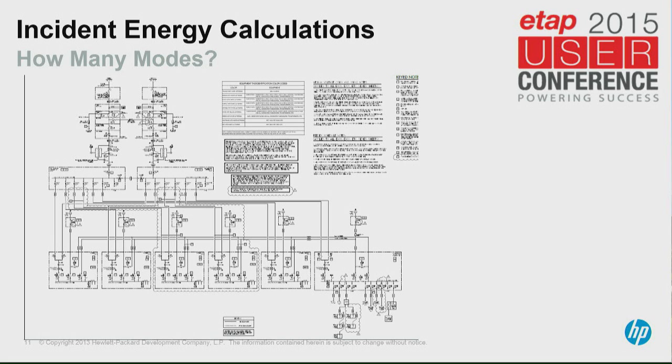When your system is a data center such as this one, how many multiple configurations do we have? What you're looking at here is an actual data center that's been constructed. It's a tier 3 data center. By the way, on the difference between tier 3 and tier 4, concurrently maintainable versus fault tolerant, this topology is fault tolerant, but we didn't go for tier 4 because tier 4 also has some physical separation, barriers and protection requirements that Uptime requires, which we didn't feel were warranted.